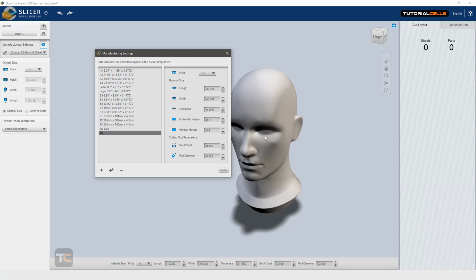First, look at your model, for example, my model is this size. See the size of it, and choose a bigger size for the length and width. If I'm in centimeters, I select a higher number, for example 1 meter, 100 centimeters, and hit enter.